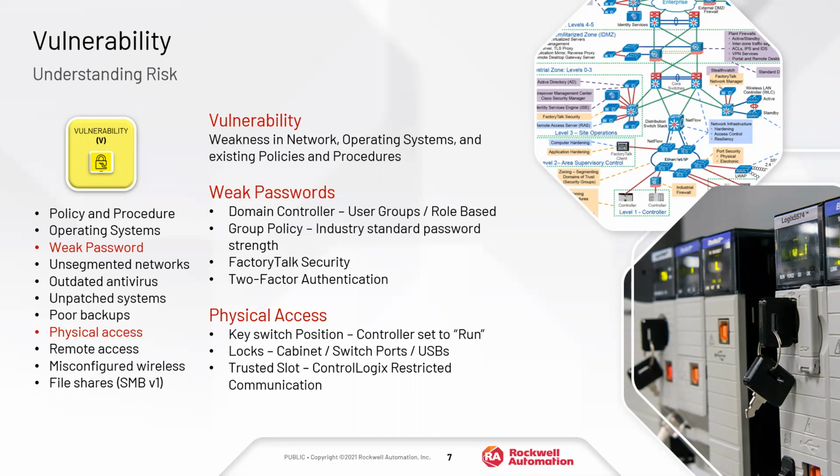The first countermeasure, the first mitigation that I'll talk about, is probably the most unpopular of the group: the key switch position. In ControlLogix and CompactLogix, what we traditionally have as a recommendation is a simple key on there for run, program, and essentially stop.